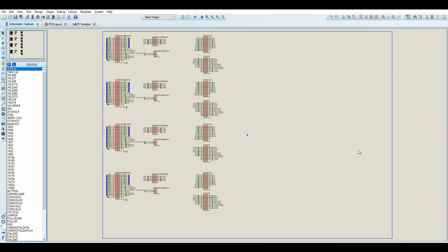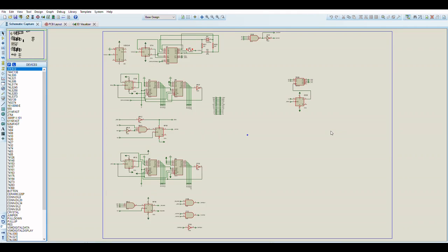So we'll go back to the original schematic here. And this is root sheet 3. Now root sheet 3 corresponds to the BombJack PDF page 3. And this is mostly to do with video timing, and the horizontal and vertical video signal generation comes from here.